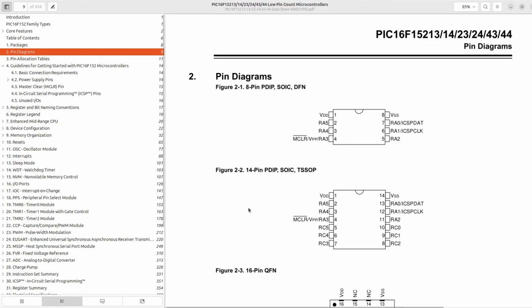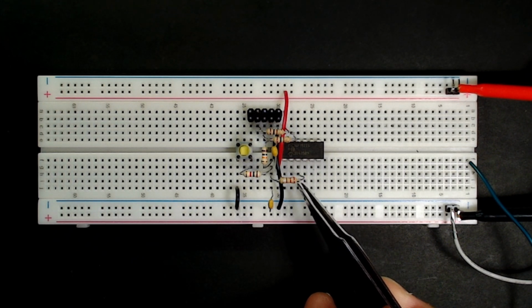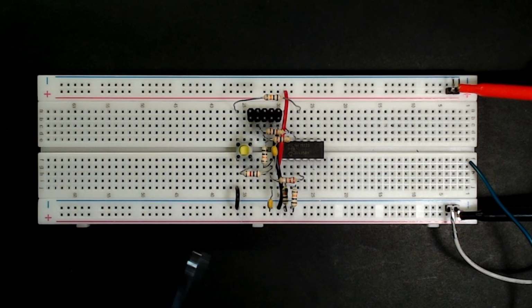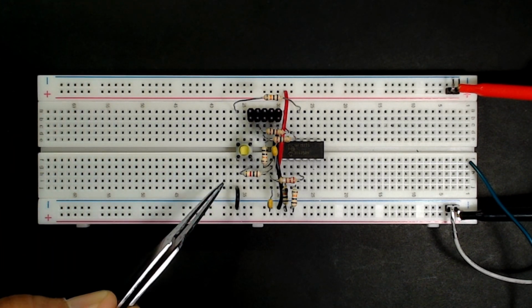And we're using the 14-pin version of the PIC16F1613 microcontroller. On port A, we've already occupied pins 0, 1, and 3 for the programmer connections. Pin 1 and 0 are up here, and pin 3 is this one right over here. But that leaves pins 2, 4, and 5 open, so we're going to connect those to ground using a 10 kilo ohm resistor. These two make a lot of sense, but if you're wondering what's going on over here, this line is connected to ground through this reset switch. It was easier to do that rather than running a wire across the entire breadboard.